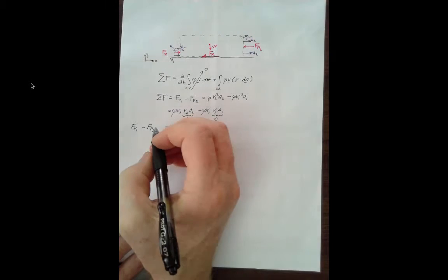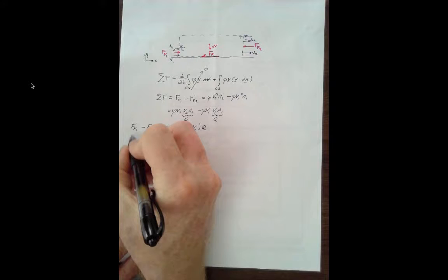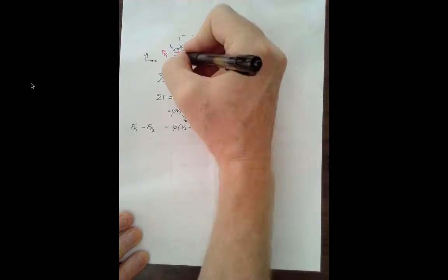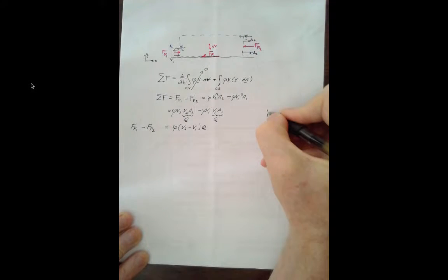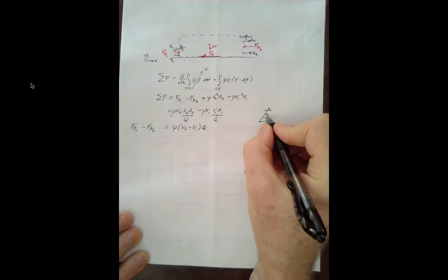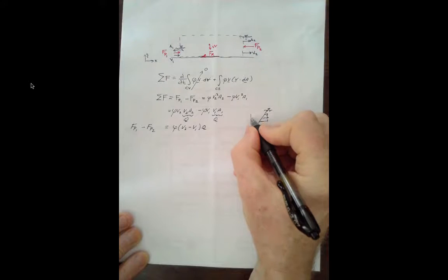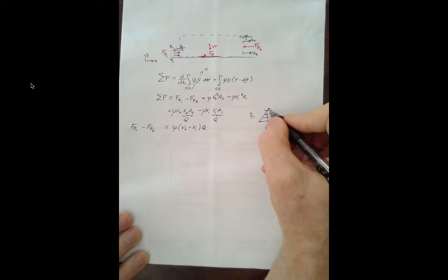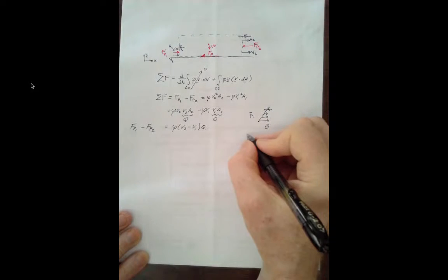Now the pressure forces, force at pressure 1. If we look at section number 1, there's some water surface, and so we would typically assume hydrostatic distribution. So the average pressure is P1 bar, which would be basically rho g y, the depth, times a half, multiplied by the depth times, let's say, the width if it's a rectangular channel.